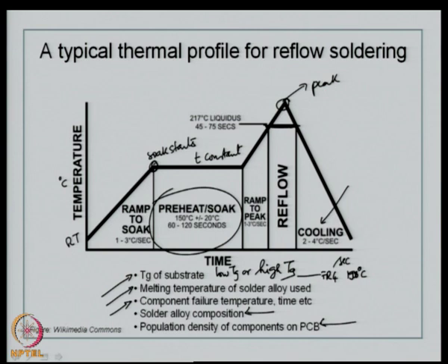If you have to use wave soldering, let us say, then it could be one wave, one reflow, okay, or it should be dual wave for double sided if you have such a kind of a choice of components. If you have two reflow processes and then a wave, then it becomes too much of a thermal shock for the substrate as well as a few components. So, use your judgment in understanding the layout of your board vis-a-vis the assembly process.